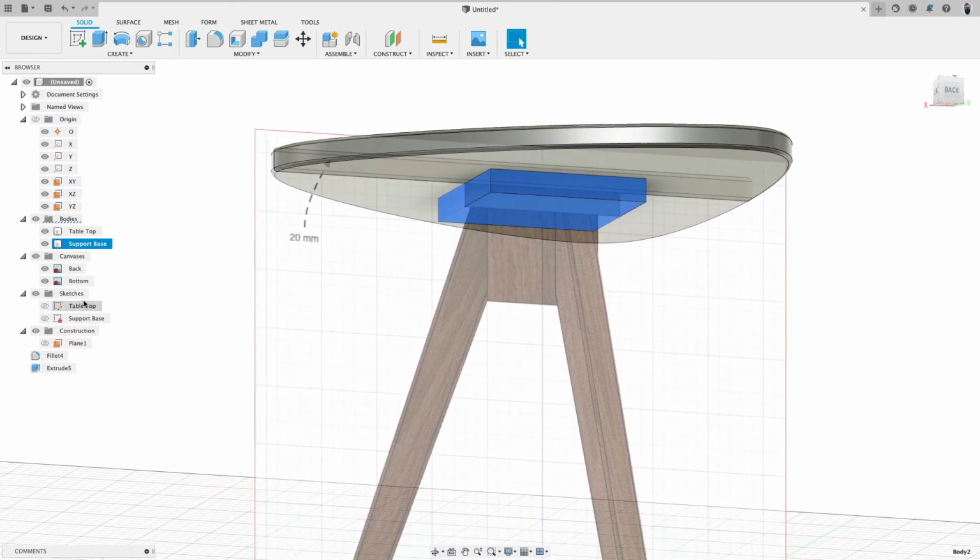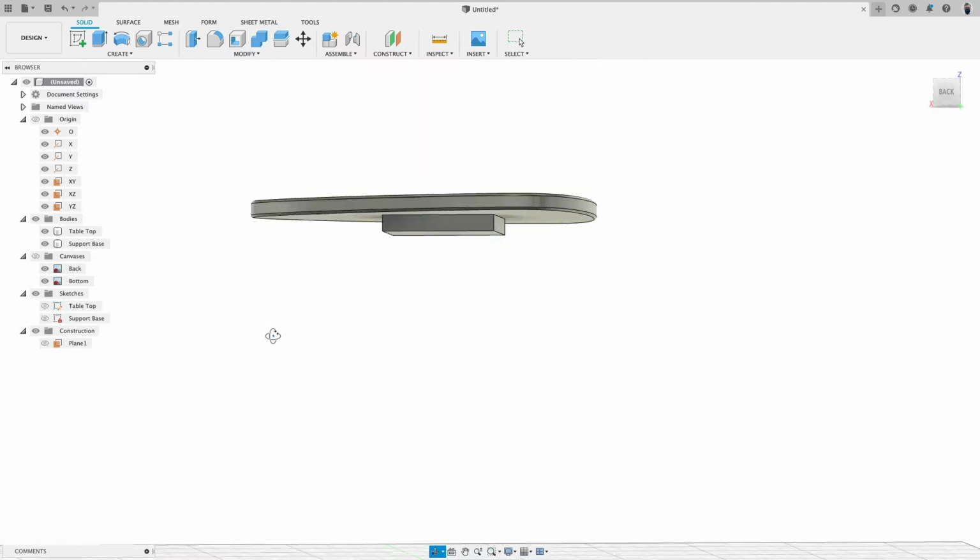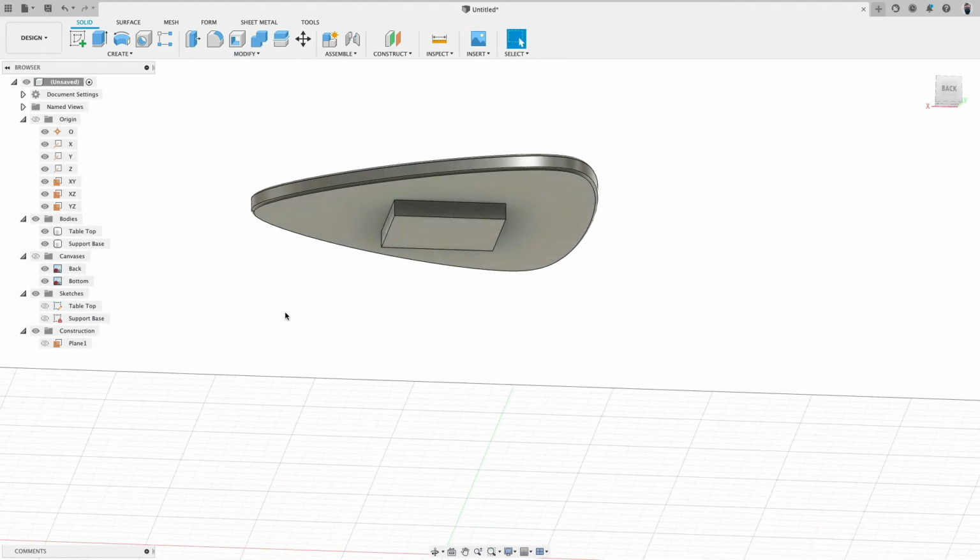I name sketches a lot. Bodies I don't really name while I did this here right now. But one big warning, if we actually, for example, start fusing elements together via the combine command, the name sometimes get changed, which is why naming bodies is not really necessarily very useful, unfortunately. So these two, right click dissolve, very good. Yeah, nice. So that's good.